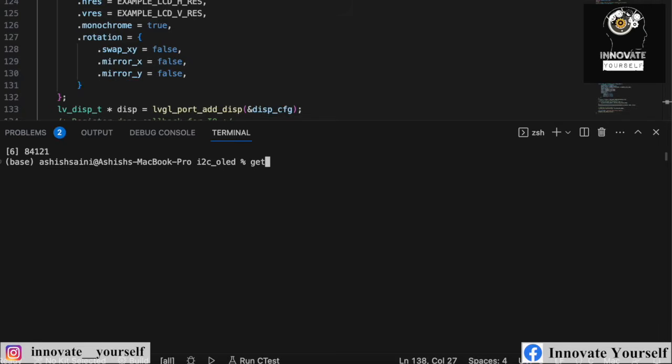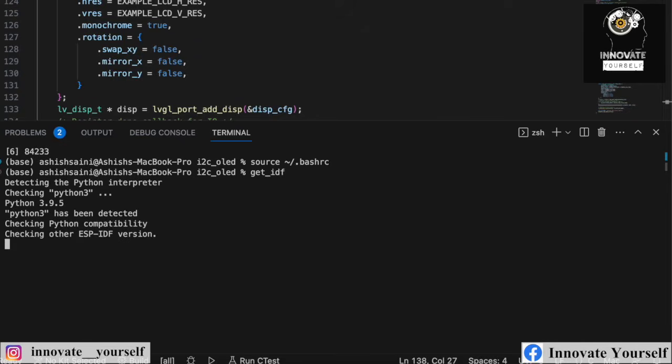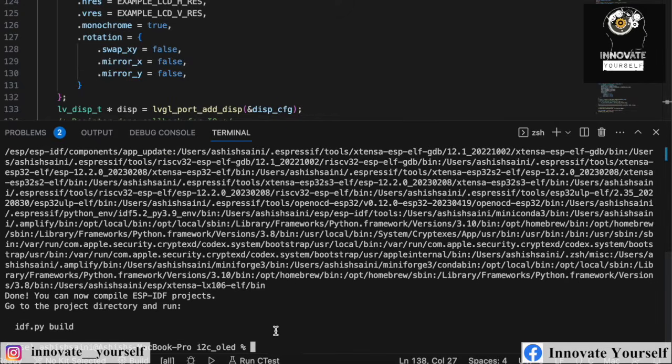Currently let me first of all open up this IDF. Let's see, is it working for me? No, it's not working for me. I'll have to delete it. Let me show you how I'm going to do it. And in fact, this thing we have already done in a previous video as well. So in case you don't know what I am doing, you can check the previous video, so you will get the clarity on that. So this is about that. Now it's going to initialize this ESP-IDF on your current terminal only. So this is what I'm doing. All right, so this is done over here.